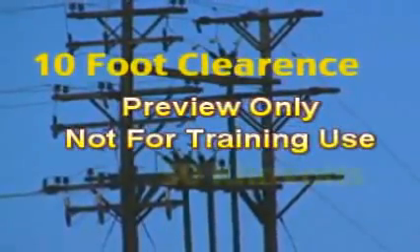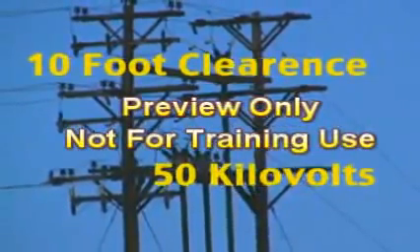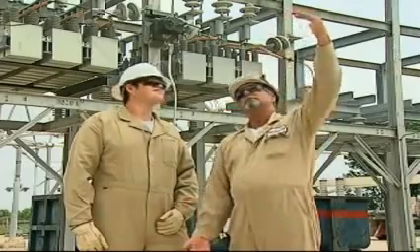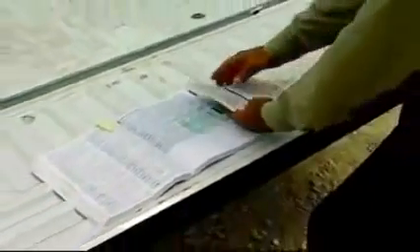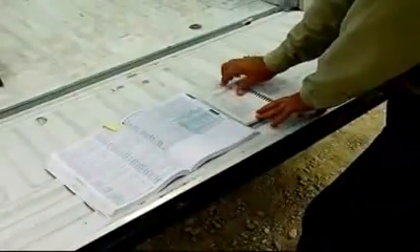OSHA requires personnel to maintain at least a 10-foot clearance of all power lines with less than 50 kilovolts. If a power line has more than 50 kilovolts, additional distance is required. Employees should consult with their supervisor to determine the proper distance needed. Electricians have different guidelines and should consult with their employers concerning this issue.